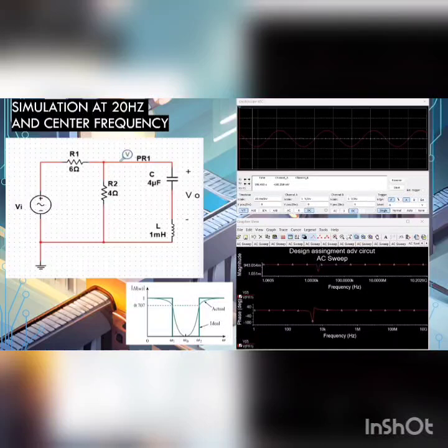Pass band ripple equals negative 20 log10 open bracket 1 minus delta P close bracket decibels, and stop band ripple equals negative 20 log10 open bracket delta S close bracket decibels, where delta P is the magnitude response of the pass band and delta S is the magnitude response of the stop band. The typical stop bandwidth of the band stop filter is 1 to 2 decades. The highest frequency eliminated is 10 to 100 times the lowest frequency eliminated. The stop band breadth is based on the difference between these frequencies.